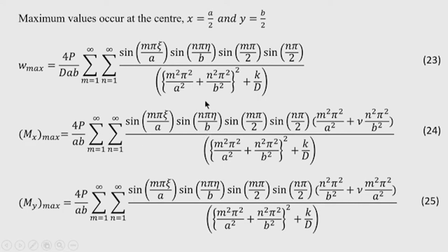In the bridge design handbook, charts are generally given for bending moment coefficient in x direction and y direction, and in this chart you will see that the bending moment expression is similar to the expression that we have discussed here, that is, the curvature in 2 directions is taken into account, but these expressions in the handbook were obtained using the simply supported boundary condition.